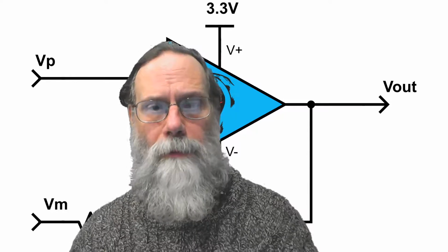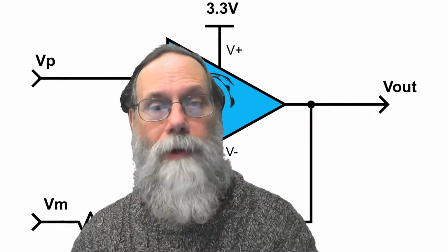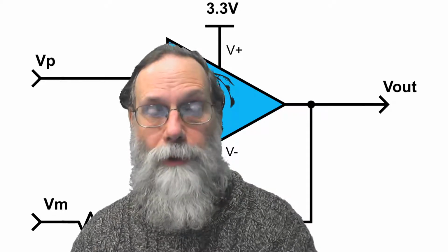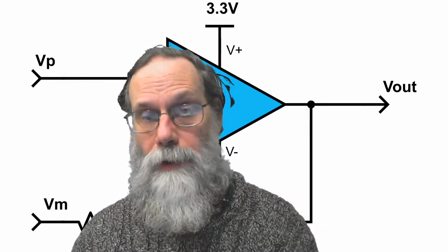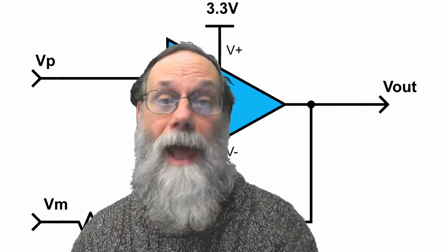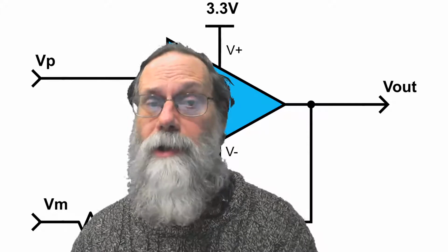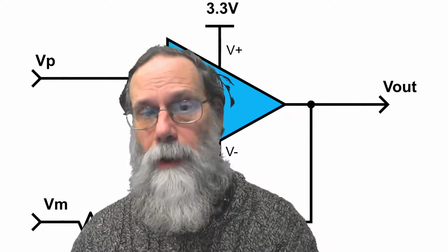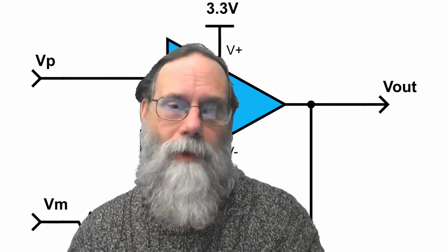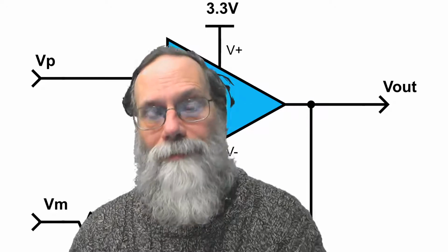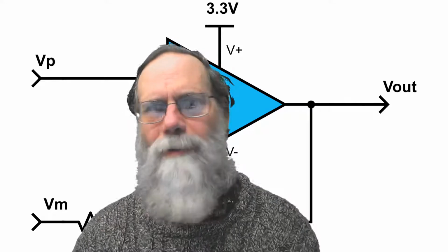Now, when we're talking about amplifiers in this course, we are usually talking about linear amplifiers. Amplifiers in which the output voltage is a straight line when you plot it against the input voltage. Technically, these should probably be called affine amplifiers rather than linear amplifiers because they're not guaranteed to produce a 0-volt output with a 0-volt input. We generally have some DC biases to deal with. But they're called linear amplifiers because the affine function is something that electrical engineers didn't remember the name for, perhaps.